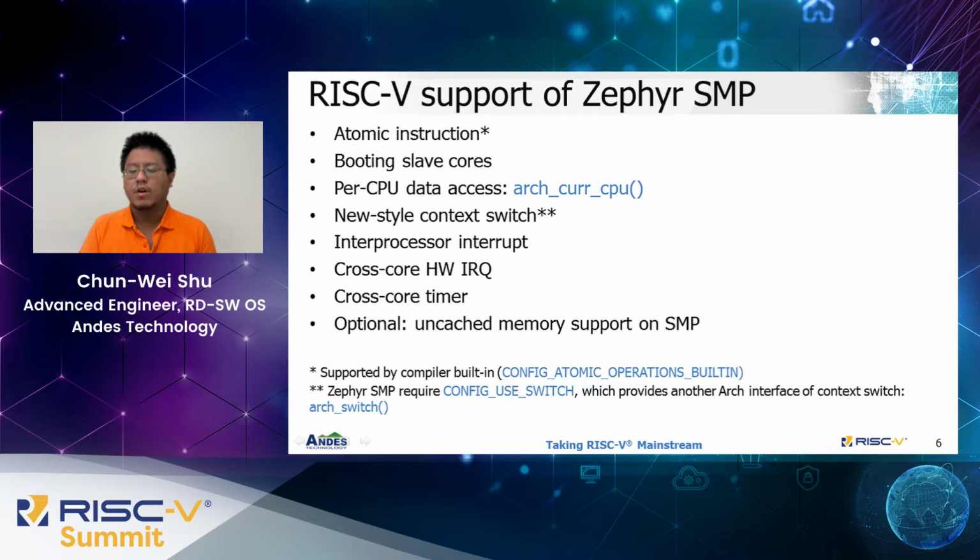Let's go to the second part of the talk, RISC-V support of Zephyr SMP RTOS. RISC-V SMP porting contains several changes in the architecture code, like the atomic instruction, booting the multiple cores, and supporting IPI. Also, we need to handle the external and timer interrupts across cores.